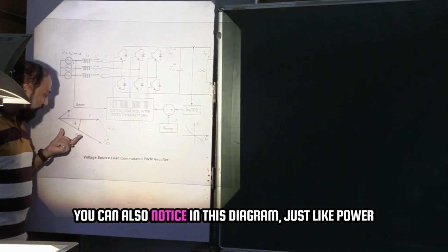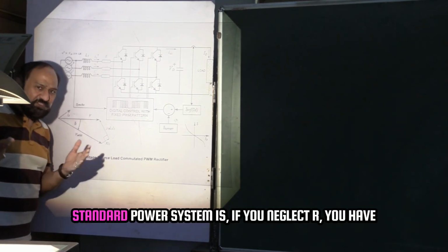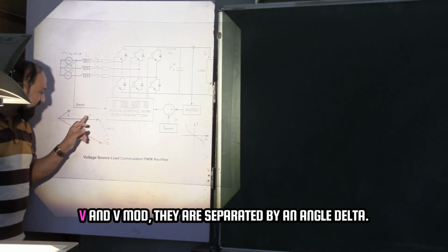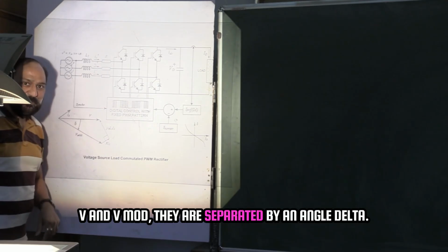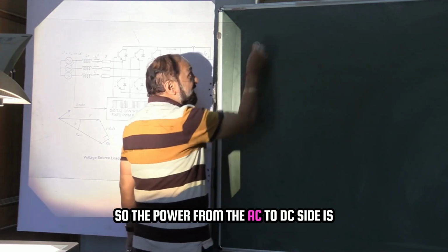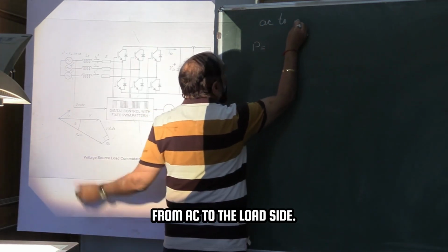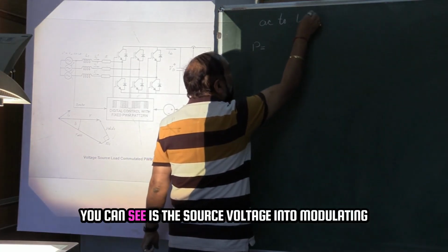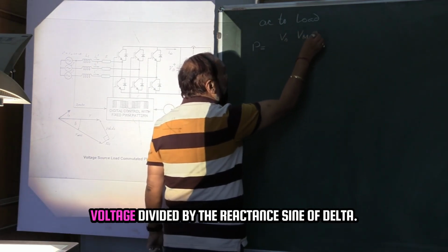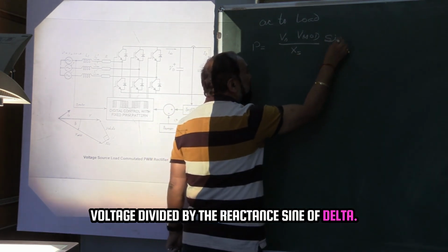You can also notice in this diagram, just like a standard power system, if you neglect R, you have V and V mod, they are separated by an angle delta. So the power from the AC to the load side is the source voltage into modulating voltage divided by the reactance, sine of delta.